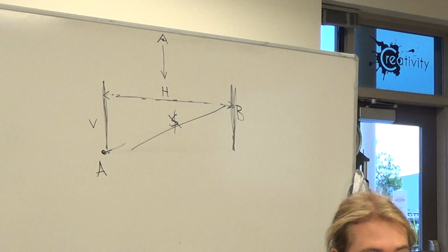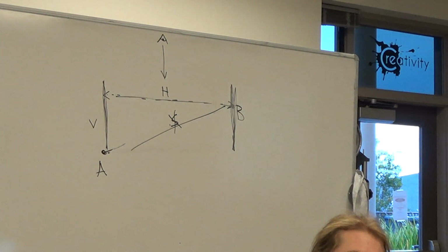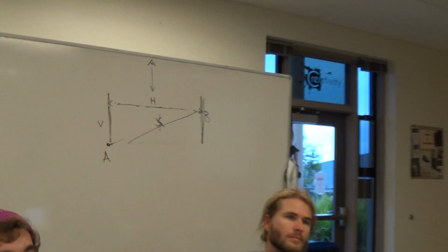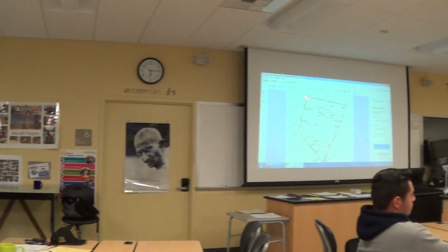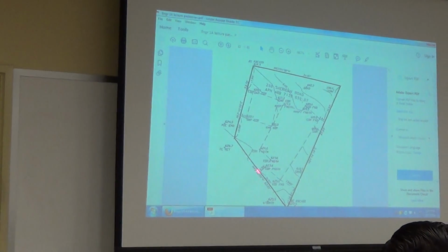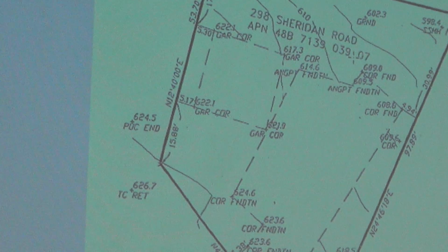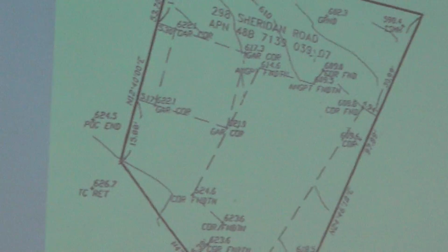So the slope of something can change over time if you move soil around, but the horizontal distance is still the same. So the distance right here from this point to this point of 74.97 is which distance? Horizontal. Okay. Here there's another 97.89. Here's a 63.21, and here's a 53.70. So those are all horizontal distances.